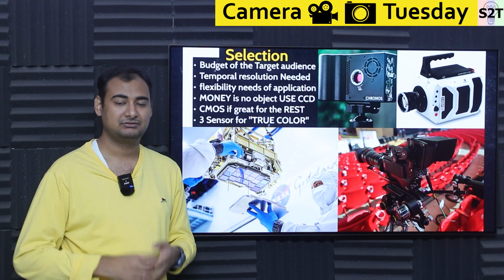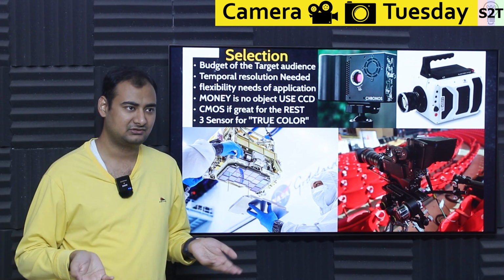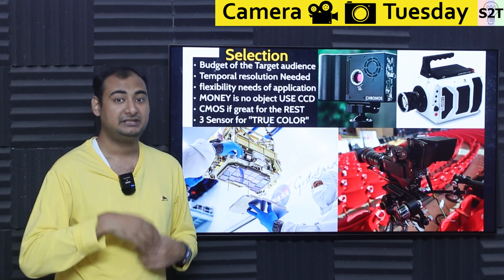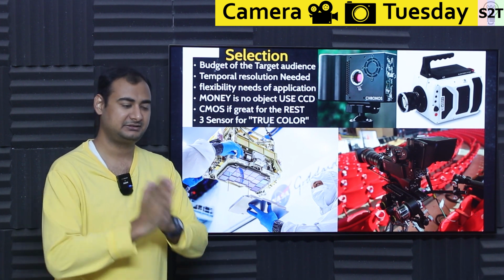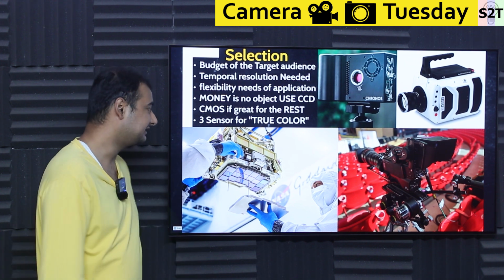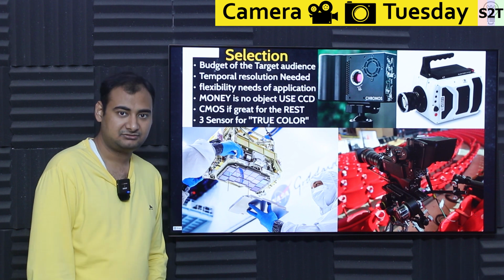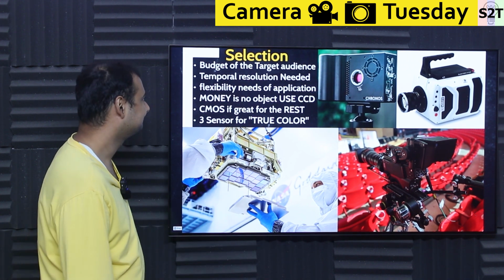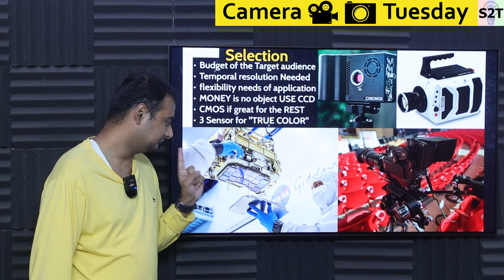broadcast to a server. So whenever you see a cricket match and everything slows down, how did they decide when to slow down? They did not bother with it. They're just recording everything, dumping it into a server. If a person at the broadcast station is like, hey, let's rewind it, then they'll rewind the 120 fps footage to, let's say, 30 fps. It can be done. Again, depending on your requirement, if you need high color accuracy and high spatial resolution, put 3 CMOS with global shutter. So selection is up to you, but this is a big sensor.